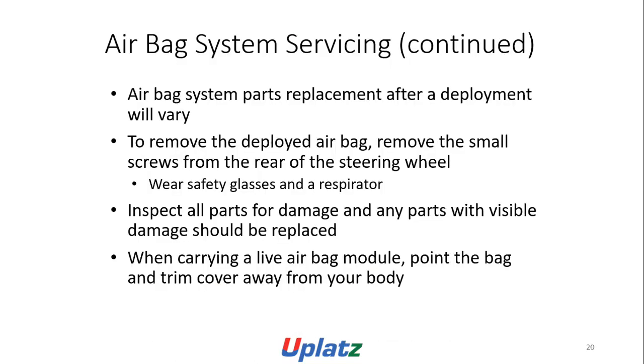Airbag system servicing. Airbag system part replacement after deployment will vary. To remove the deployed airbag, remove the small screw from the rear of the steering wheel. Wear safety glasses and the respirator. Inspect all the parts for damage, and any parts with visible damage must be replaced. When carrying a live airbag module, point the bag and trim cover away from your body.